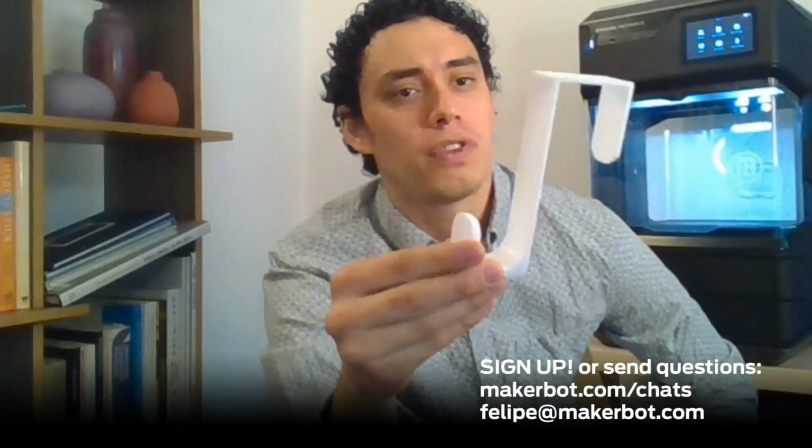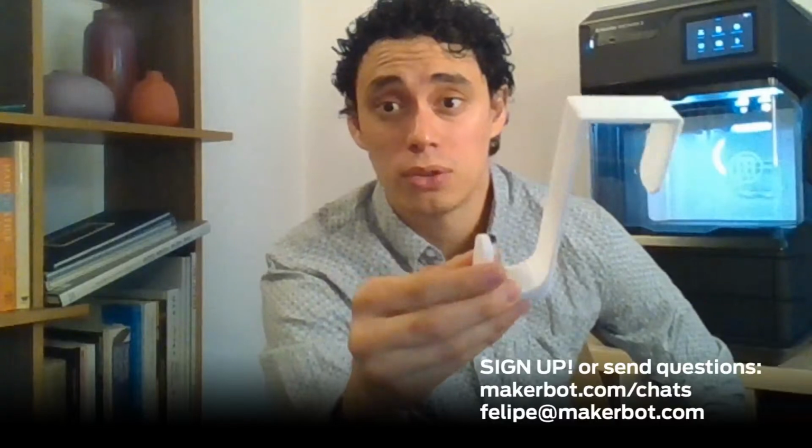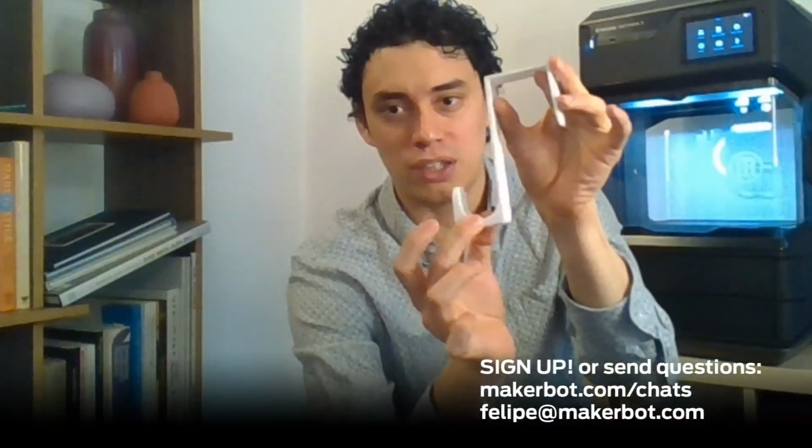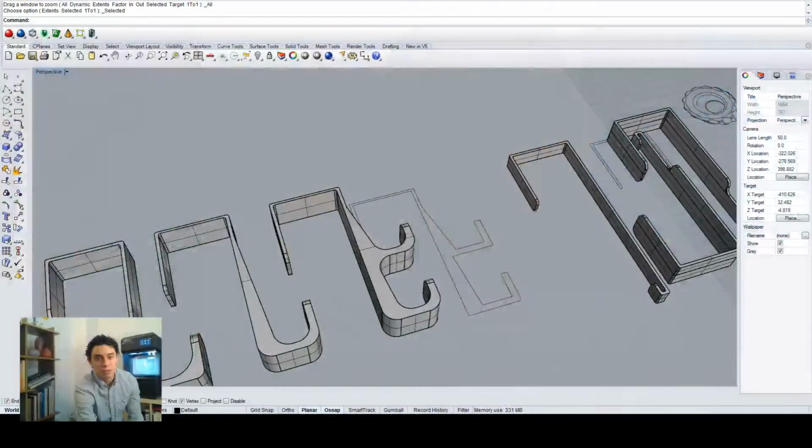Because the challenge here is that you're trying to create something fairly robust. This needs to withstand at least a good 5 to 10 pounds, so that's 2 to 5 kilos, depending on whether you have a wet towel or the dryer hanging in there. And you do get some structural help from the door itself, right? As this nests in the door, the door is going to prevent this frame from cracking or bending. However, as you try to make it thinner and optimize it, then it becomes a little bit trickier. As you add functions too, it becomes a little bit trickier.